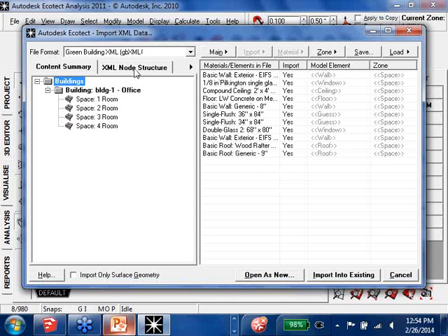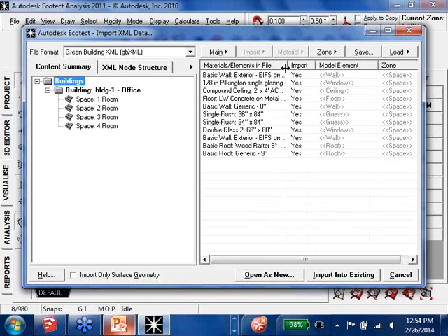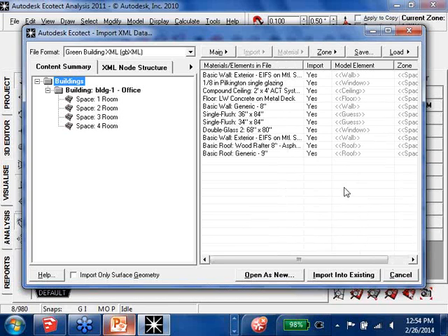Even though you get to this point, you can see that it's identifying these materials as a class: roof, wall, window, or whatnot. So it can then apply Ecotect's default materials to the surfaces that have these materials applied to them. So we're not getting these materials into Ecotect. We're just translating them to Ecotect's defaults.